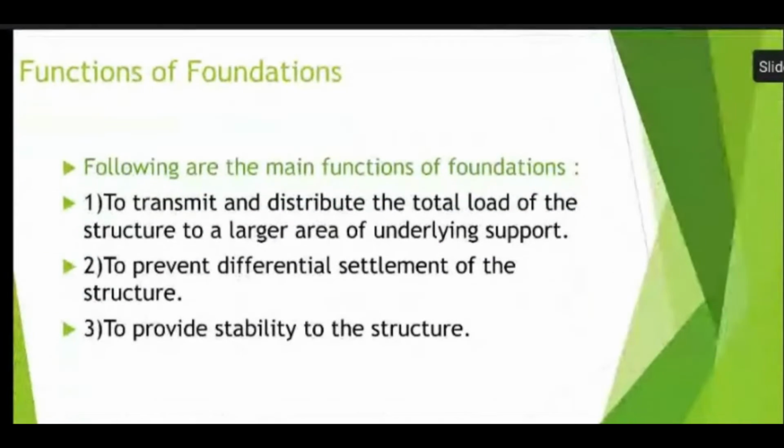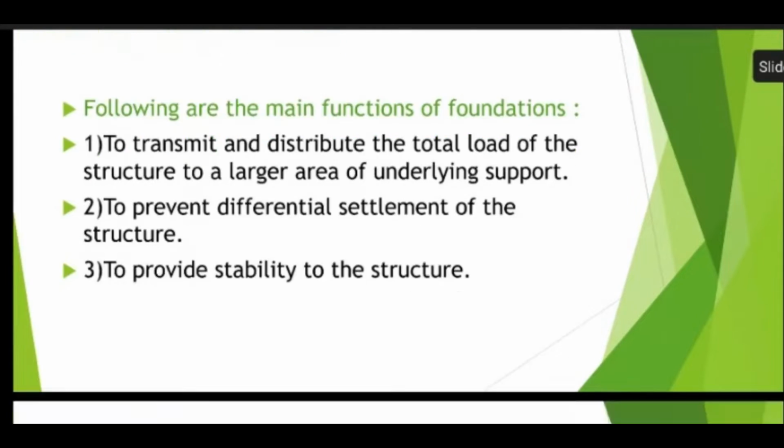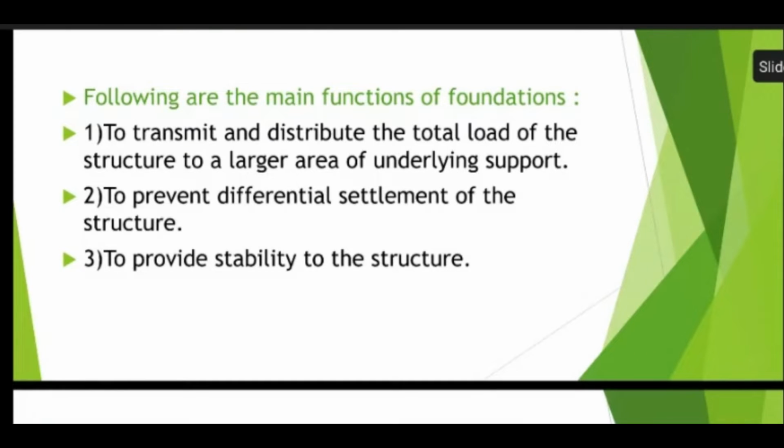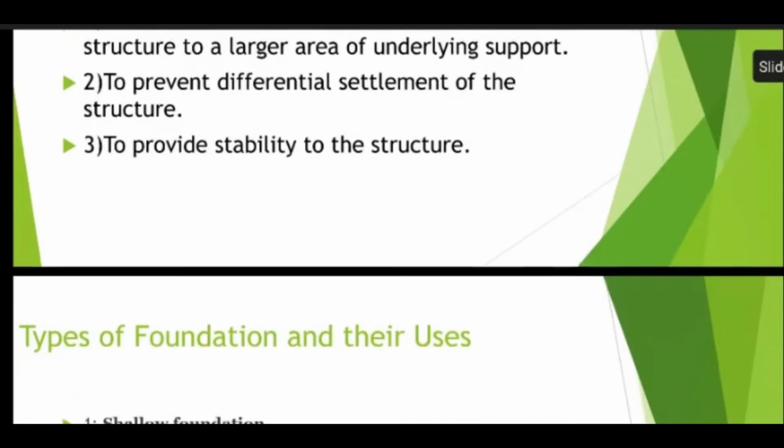Functions of foundation. Following are the main functions of foundation. First, to transmit and distribute the total load of the structure to a larger area of underlying support. Second, to prevent differential settlement of the structure. Third, to provide stability to the structure.